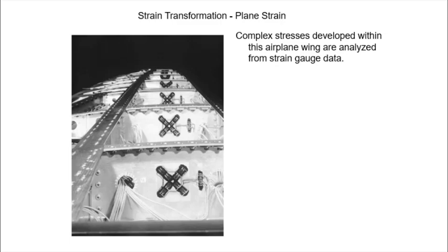So this here is an array of strain gauges. There's two on each arm, one there and one there. So total there's 8 strain gauges, and this arrangement is called a rosette. Okay. So when we do tests on the structure, we will put some sort of strain measuring device, and strain gauges is one form of a device to measure strains.